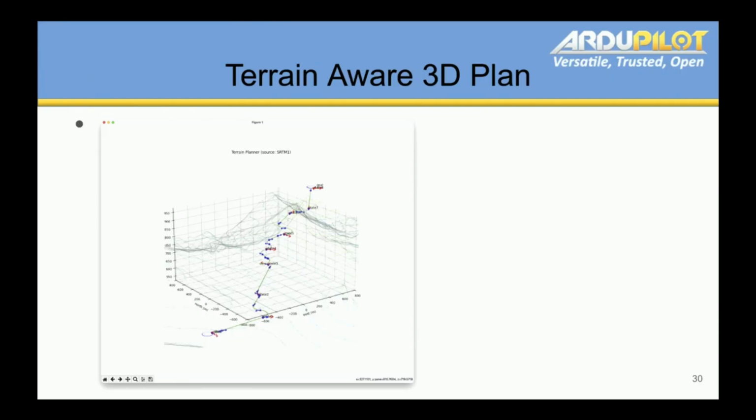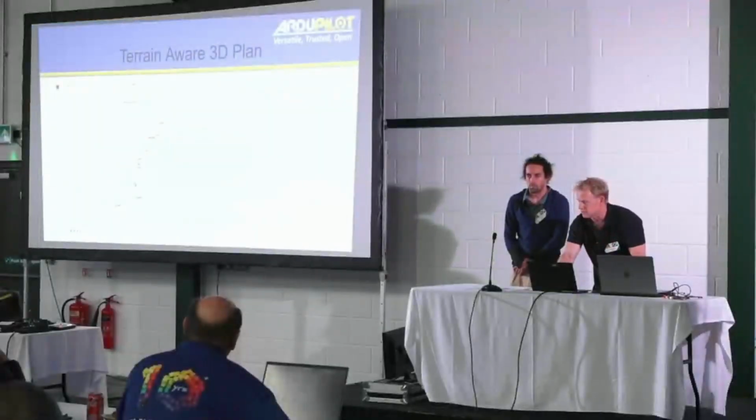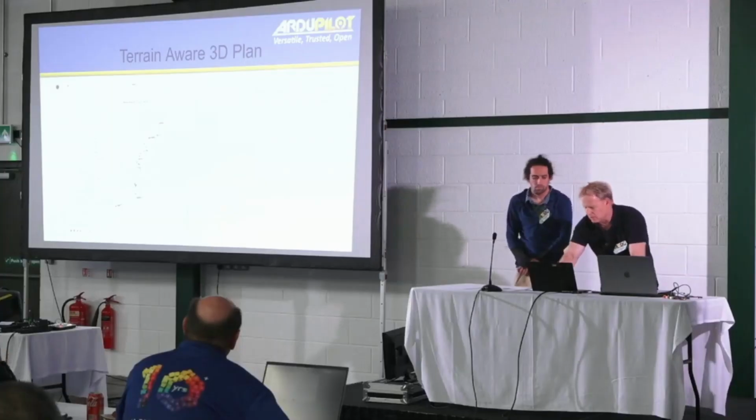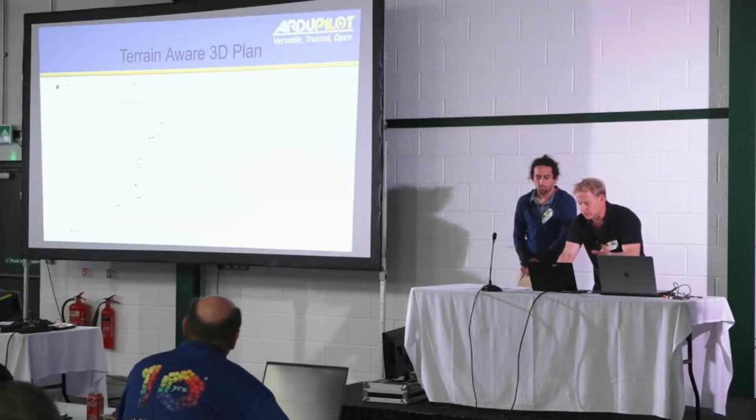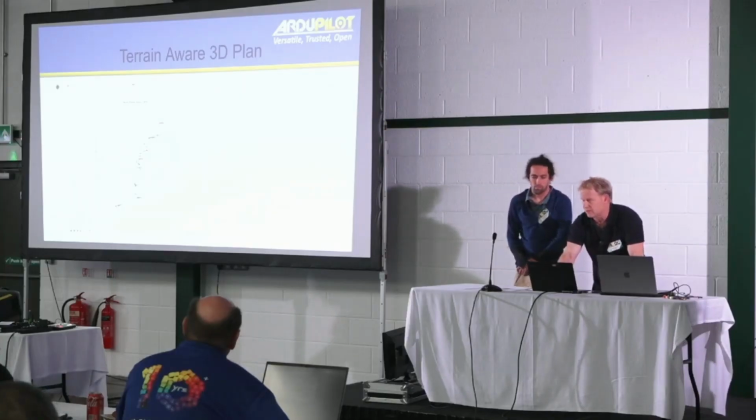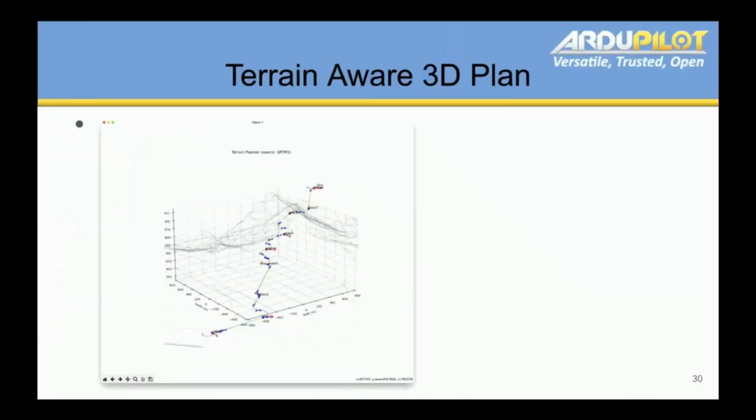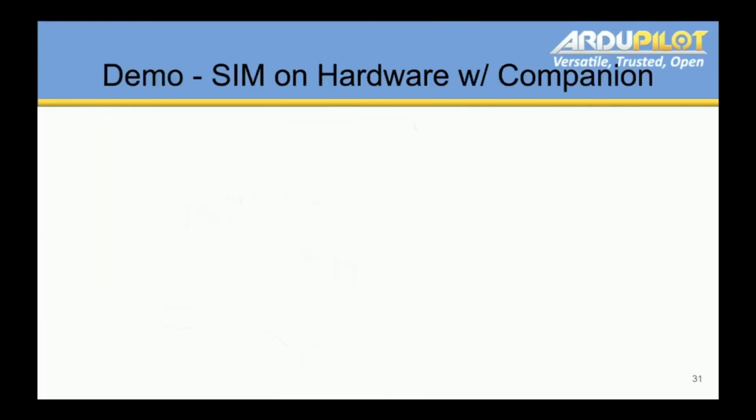It's a random sampling planner, and the way that OMPL works, it tries a different state sampler each time. So if you rerun the planner, you'll get a different route. And that can be useful if it can't find a solution the first time. I think one of the things about figuring out how to initialize it well, so that if you want to force reproducible results, would be useful. It does have a facility in it, but we don't have that shown at the moment.